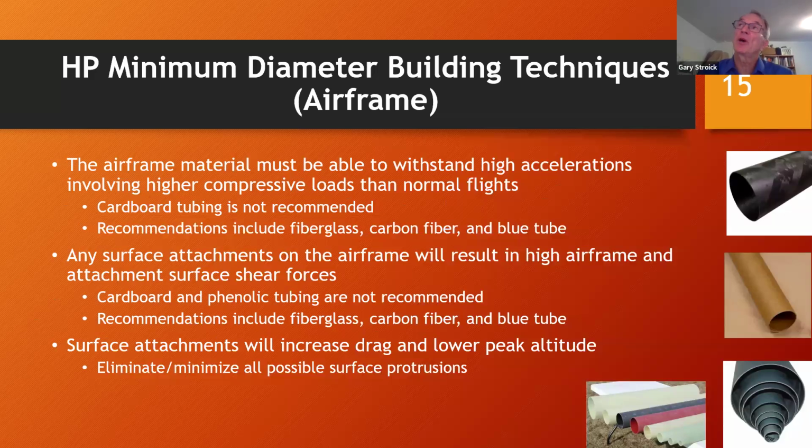And of course, this also refers to, since these are being attached to the airframe, the material used for joining also needs to be strong enough. And so the white glues and so on that you may have used in model rocketry are just not appropriate. You really need to use epoxies to hold these in place, or some other kind of fastener, screws and so on.